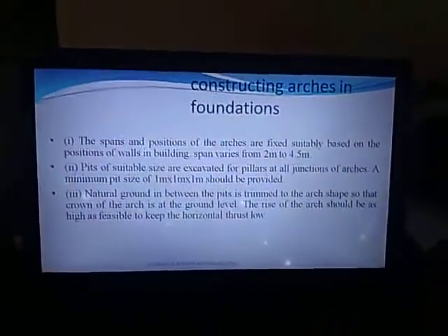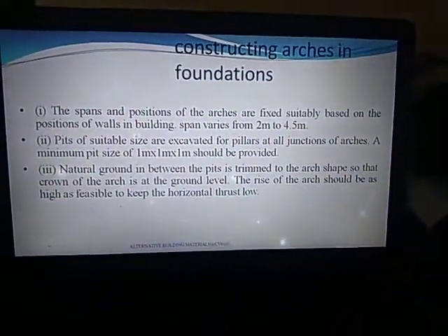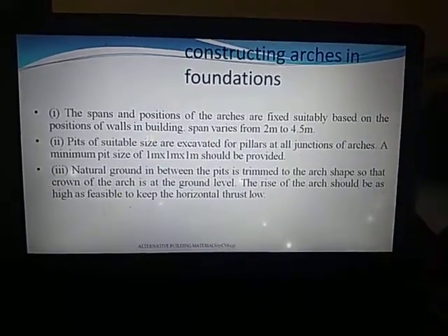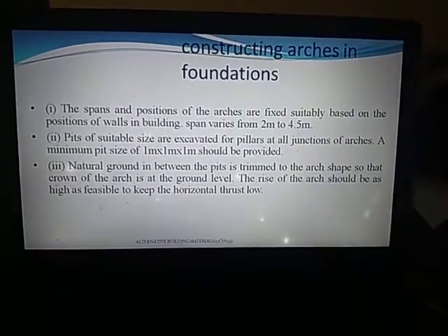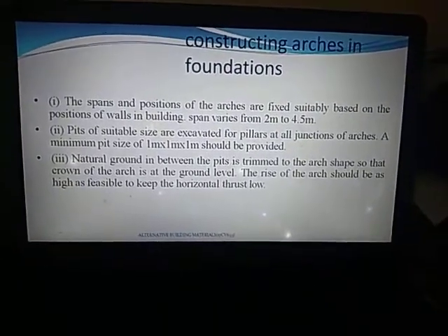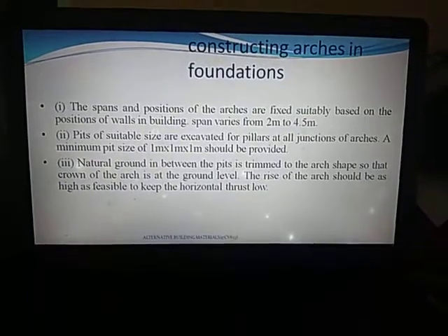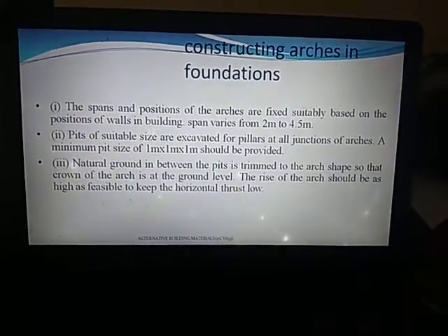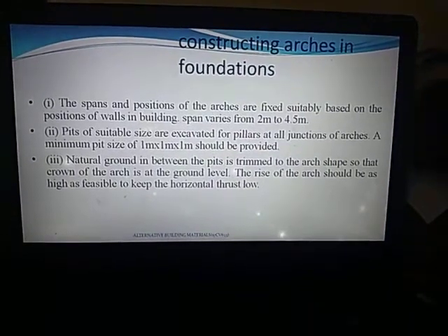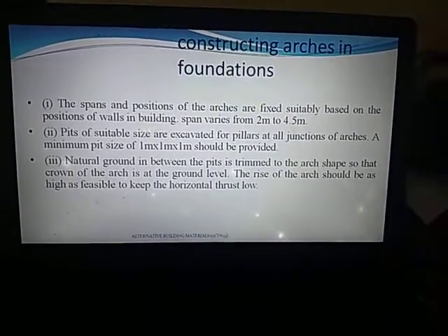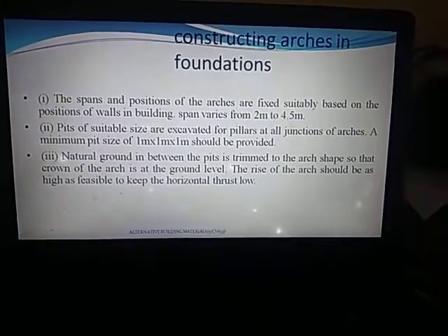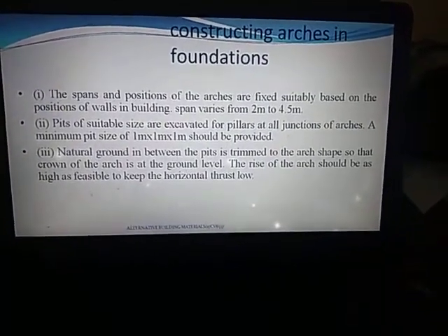So next I am going to explain constructing arches in foundation. While constructing arches in foundation, the spans are very important. The span and how the arches should be laid, the position of the arches, that is very important. Therefore, first you have to fix the span and position of the arches. The span and position of the arches are fixed suitably based on the positions of the walls in the building. Usually we will take a span varying from 2 meters to 4.5 meters.